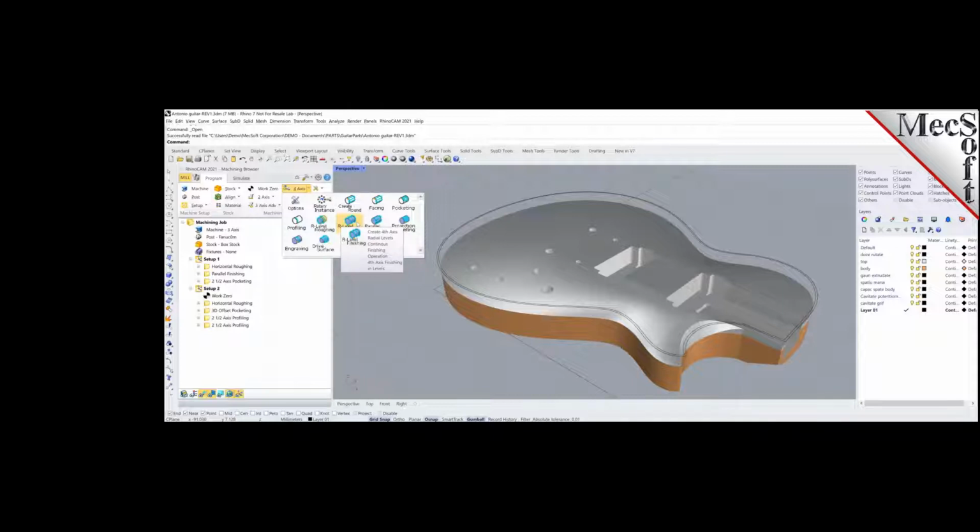There are many types of parts that you can machine with the wrap function, and I'll show you a few of those. And then we have parallel finishing, and these are more advanced methods. These are called projection machining, so you're actually projecting it onto the 3D model. And then finally, we have the drive surface machining, which is basically our advanced premium technology, which is using surface models to create the drive path. I'll get into that a little bit.